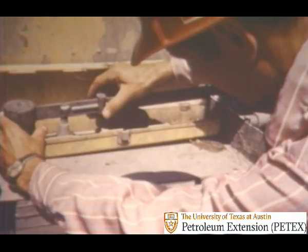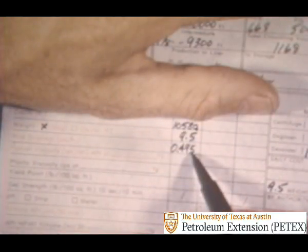Next, the mudman weighs the mud in a mud balance. Weight may be in pounds per gallon, pounds per cubic foot, or kilograms per liter. Mud weight is important because it keeps formation pressure in check and affects the drilling rate. The mudman records the weight, in this case 9.5 pounds per gallon.